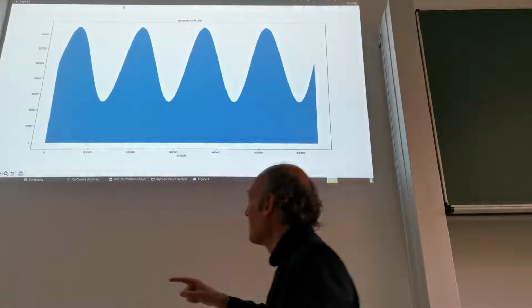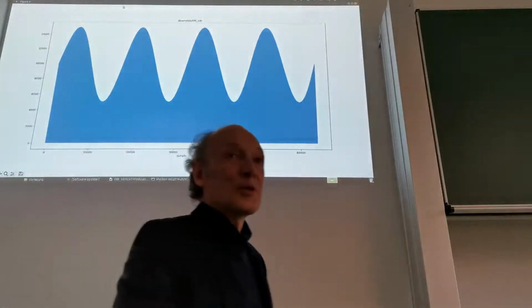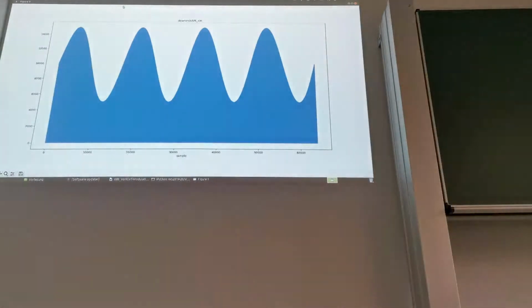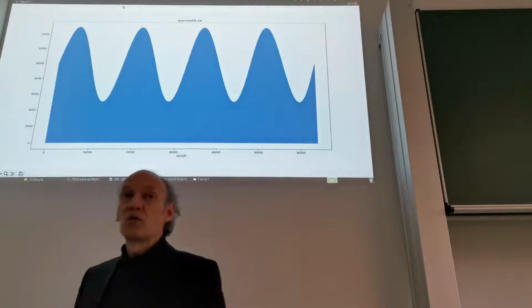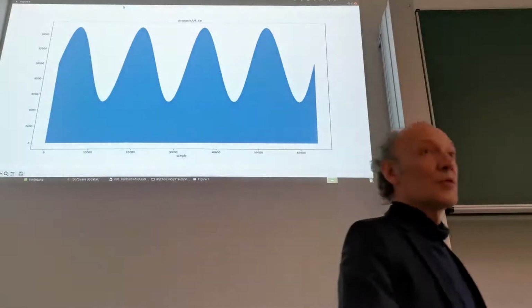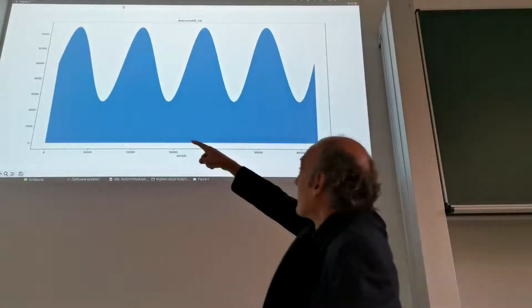And you can also see that it's all positive. This comes out of the sine carrier being the right phase. The sine now has exactly the same phase as the carrier from the transmitter side. So basically we downmixed it to frequency 0, and this is the DC offset that we used for modulation. Remember, we have this 1 plus 0.5 times tone, and this is exactly what we now see here.